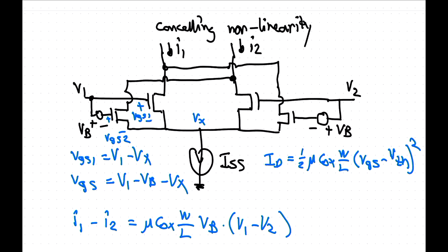Transconductor filters might be something that you find, but quite typically for filters, it's not very common that a filter chip has a predefined cutoff frequency. It would be more common that you can control a cutoff frequency in some way. You normally do that with external components, and that's kind of where the trimming comes in.